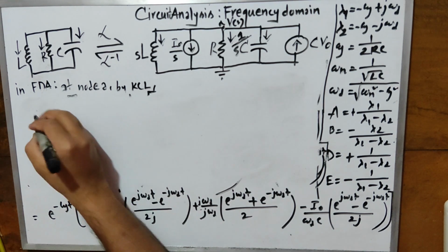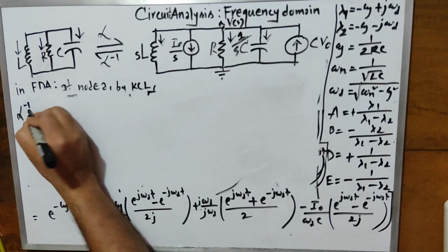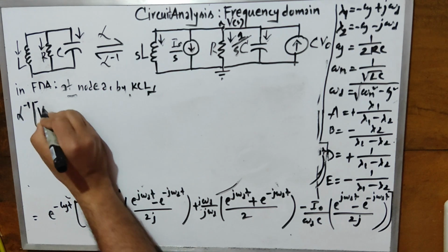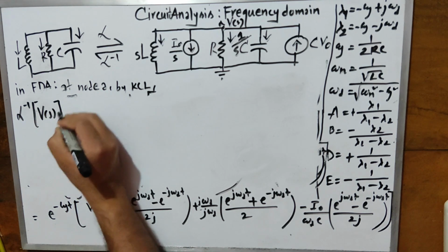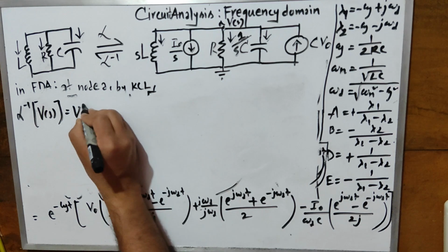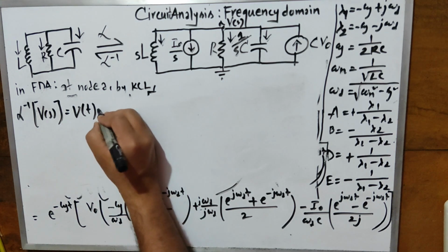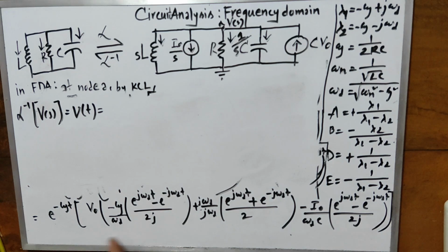Okay, so the inverse Laplace transform of the node voltage V(s) gives the node voltage in the time domain, which gives us this.